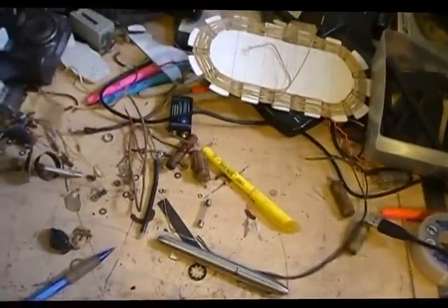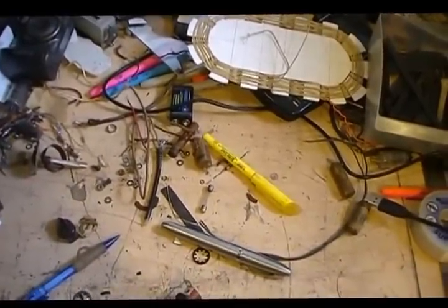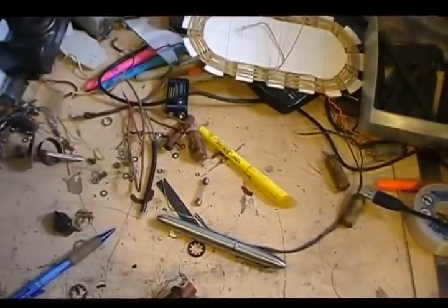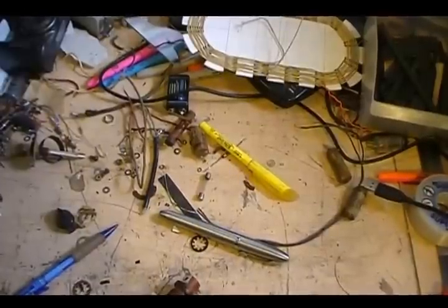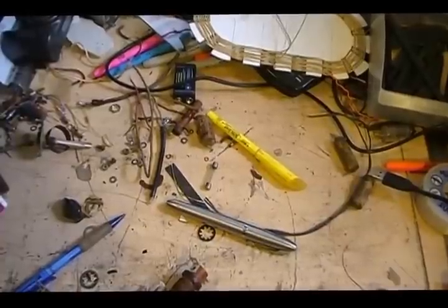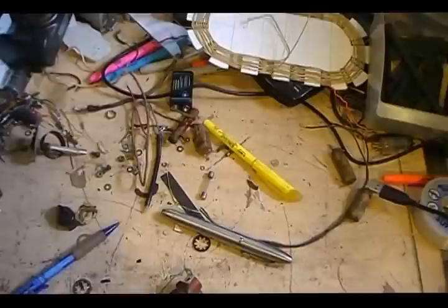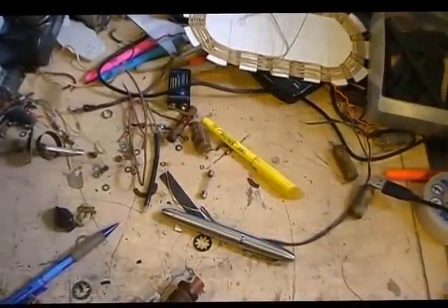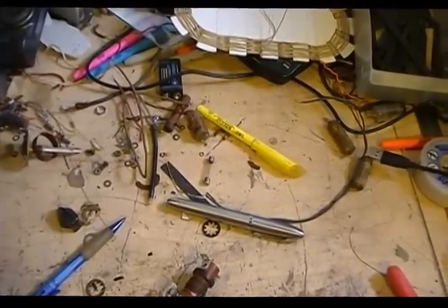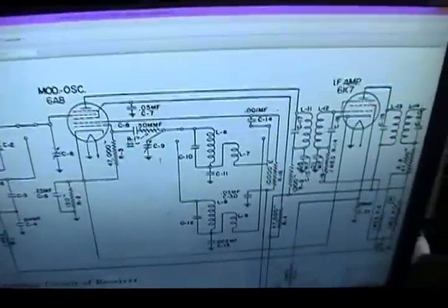The other thing is to start looking for common points. In any oscillator, the two coils that make up the basic coils or transformers of the oscillator and the antenna coils, no matter whether it's a Hartley or a Tickler coil or Armstrong, one end of those coils is going to go to a common neutral, more or less, basically in the oscillator section.